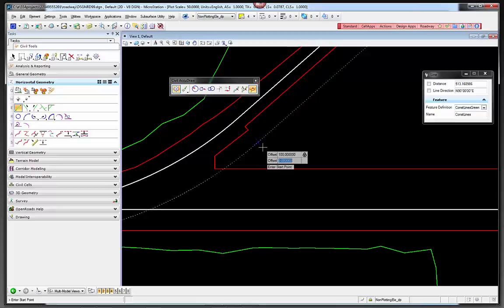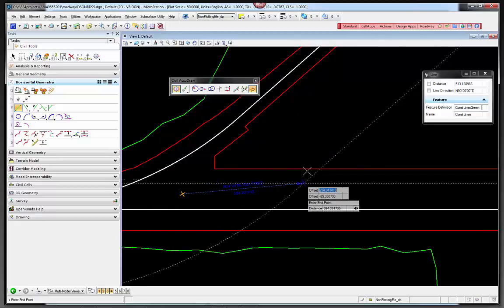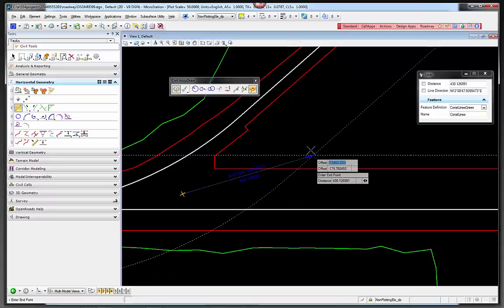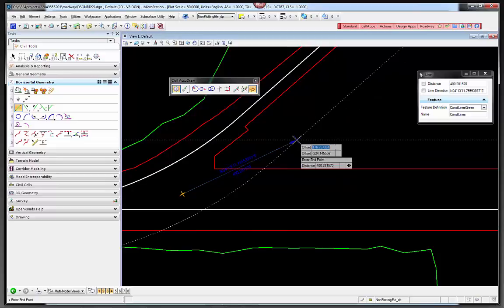on that offset. And then for the second offset, what I want to do is find the point, find where it's 50 feet from this other line. So I'll key in O with my focus in that second offset field, and I can select this line, and then I can lock this value with the focus at, let's say, -50. And now I've located that point, and that's the start point. And that's how you can find that one. And it remembers the two lines that you're trying to work off of.